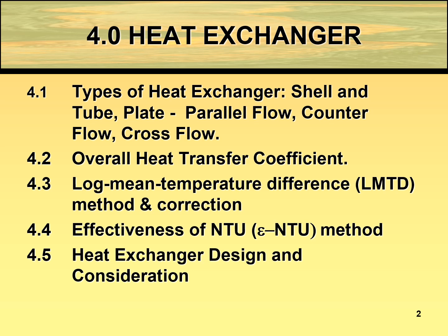And then you're going to look at the correction factor, which you need to use if you apply the LMTD method. We're going to look at the chart provided by previous investigators. And then the second method for analyzing the heat exchanger is the effectiveness NTU method, which is the second part. And then finally, very brief on the heat exchanger design and considerations.